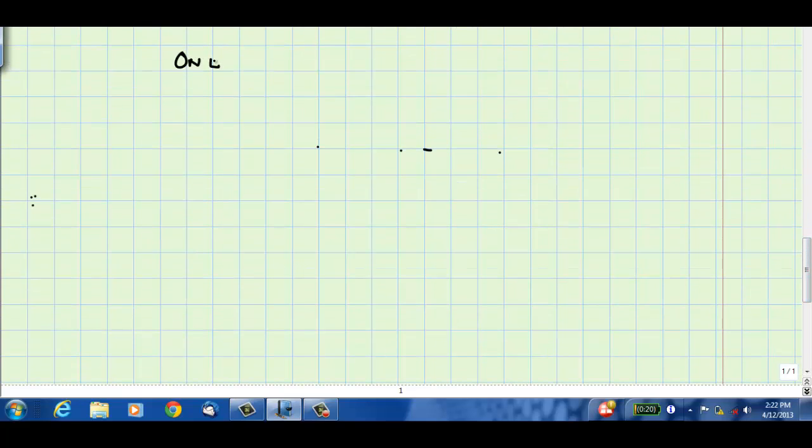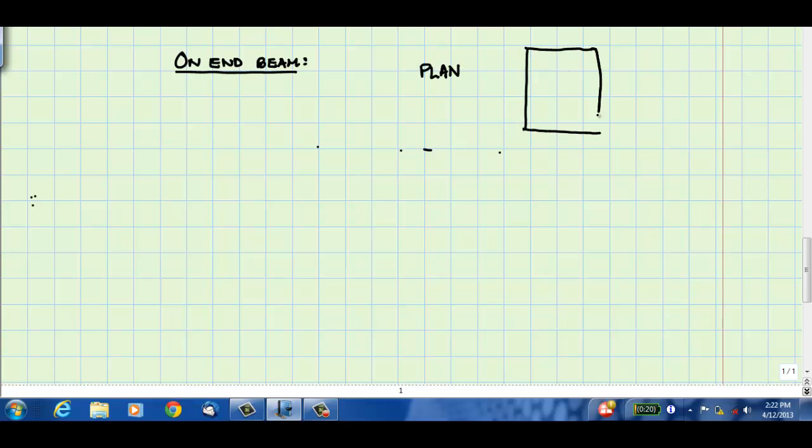We can do an identical investigation on the beam along the 14-foot edge of the floor. Looking at the plan view again and drawing the 45-degree lines, we see the tributary area now is triangular.